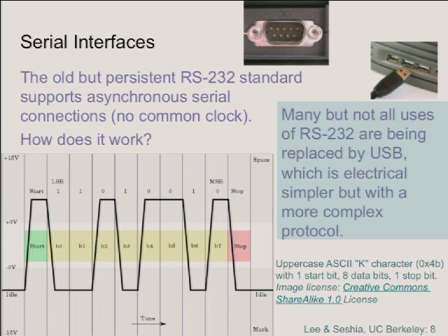So if you want to support RS-232, you have to put voltage converters on your hardware to convert your 3-volt supply to a 12-volt supply in order to be able to drive RS-232 devices. So it's really pretty awkward to actually use raw RS-232.